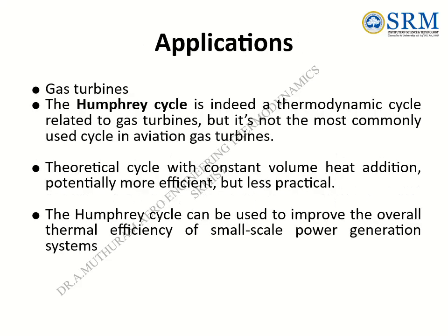Gas turbines. The Humphrey cycle is indeed a thermodynamic cycle related to gas turbines, but it's not the most commonly used cycle in aviation gas turbines. It is a theoretical cycle with constant volume heat addition, potentially more efficient, but less practical. The Humphrey cycle can be used to improve the overall thermal efficiency of small-scale power generation systems.